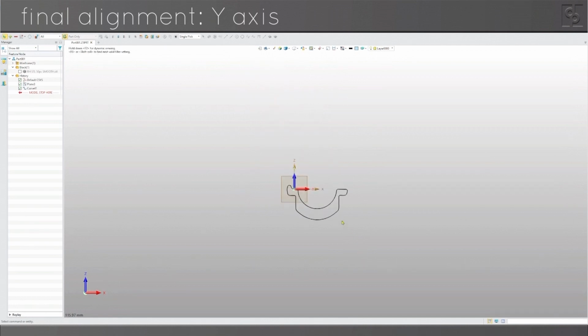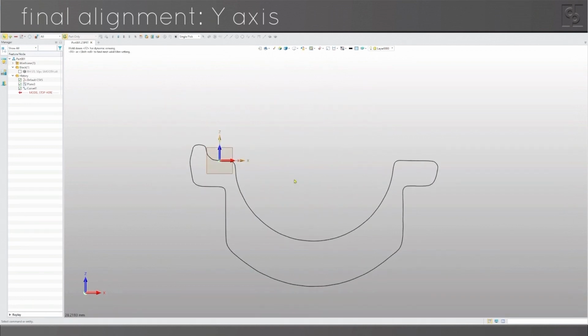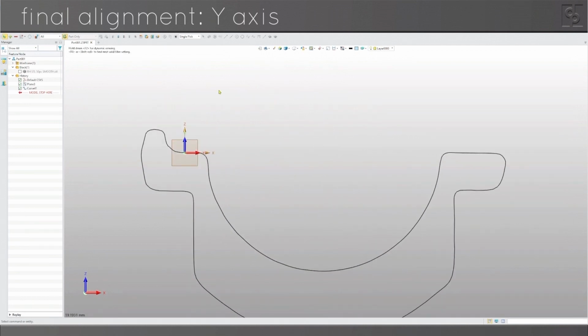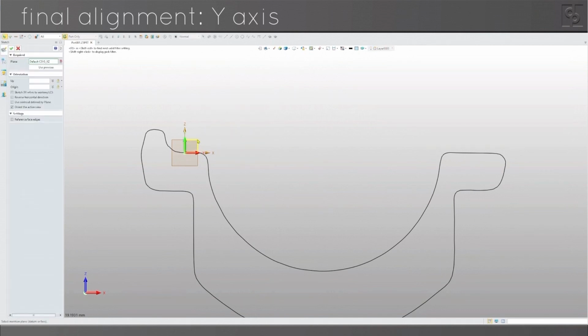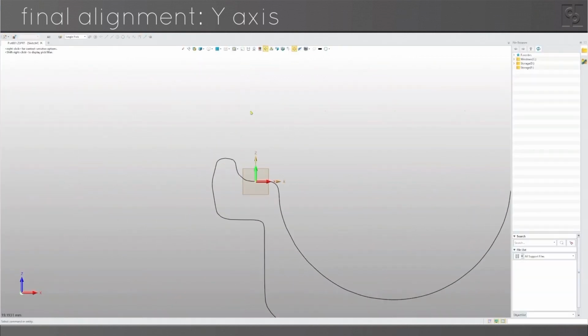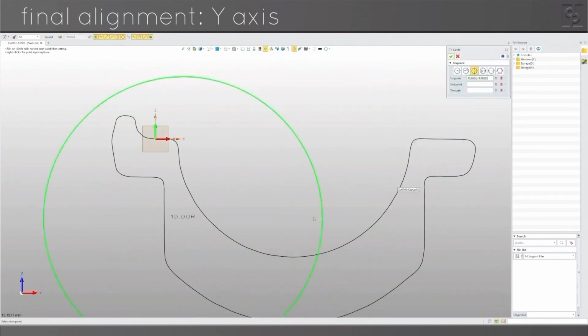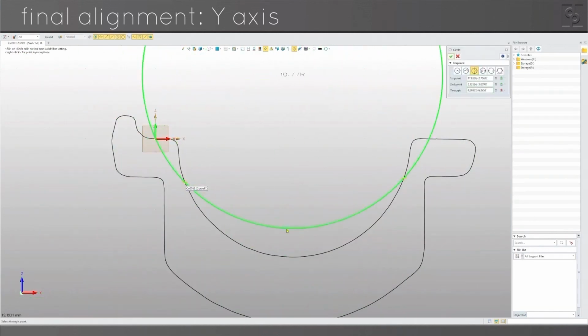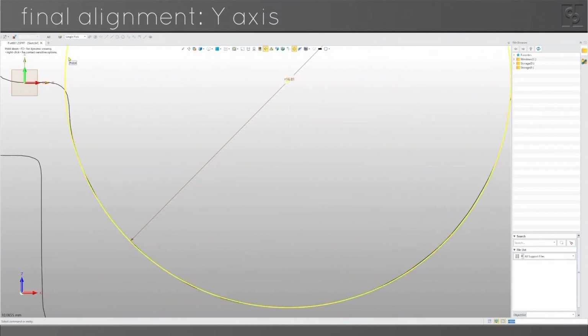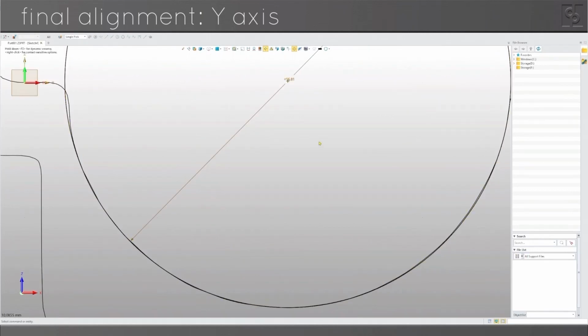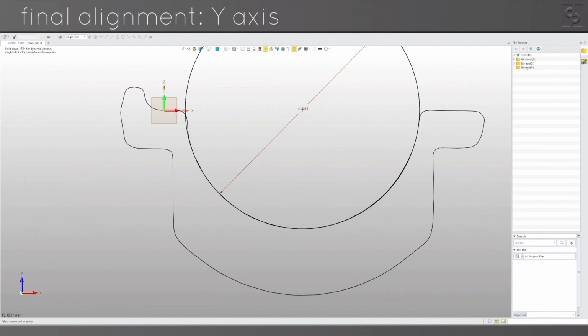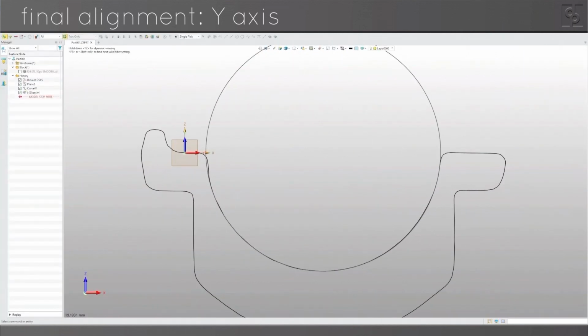And when I've cut the section, instead of making a straight line this time, I'm going to create a sketch with a 3-point circle. Because this is an injection molded part, I expect the ends of the circle to possibly be drafted straight lines. So I'm going to pick the bottom 3/4 of that circle for my 3-point arc.